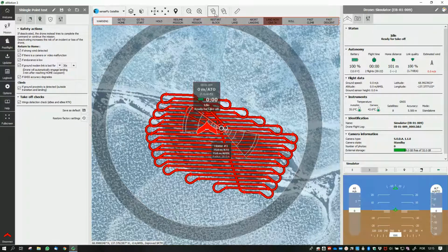If you click here, this button shows the footprints of the photos which you already took. So you may want to toggle it sometimes to check if you have already covered the area or not. And remember, when you are doing several flights, you want to be sure that these sectors are covered with an extra number of photos. So just do small overlaps between areas which are close together.